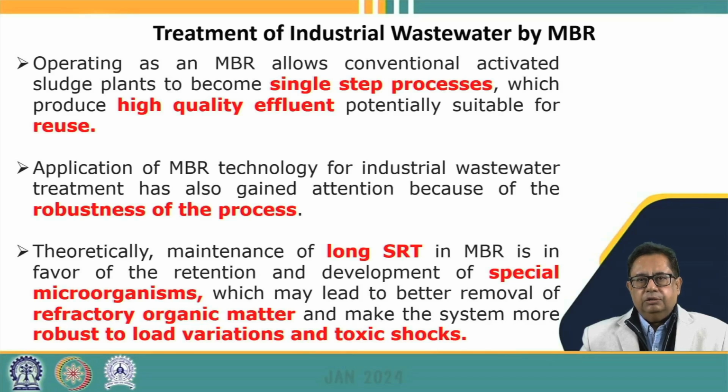Okay, so the use of MBR technology for industrial wastewater treatment has gained attention because of the robustness of the process. The robustness comes from the long SRT that can be maintained in the membrane bioreactors, because we know that the membrane retains the biomass and does not allow it to go outside the reactor, which leads to a long sludge retention time, or we can say the sludge age increases. Because of this, certain special microorganisms can develop, which may lead to better removal of refractory organic matter, which otherwise may not take place in the conventional treatment systems.